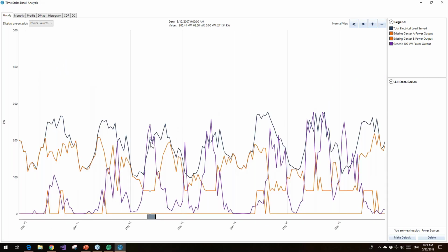So when wind is high, you can put the one generator down at minimum load and turn one generator off completely. So in this way, you can really dig deep into the details of the system and understand that the dispatch is operating correctly. You trust that this is going to give a good representation of the economic results, everything like that.